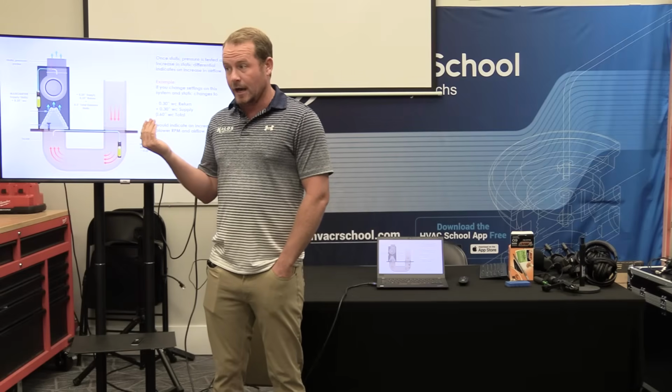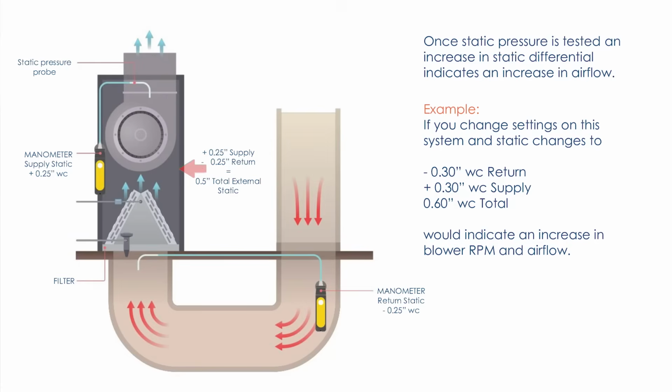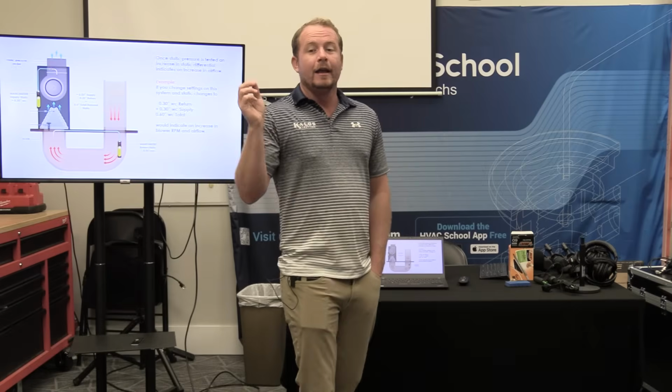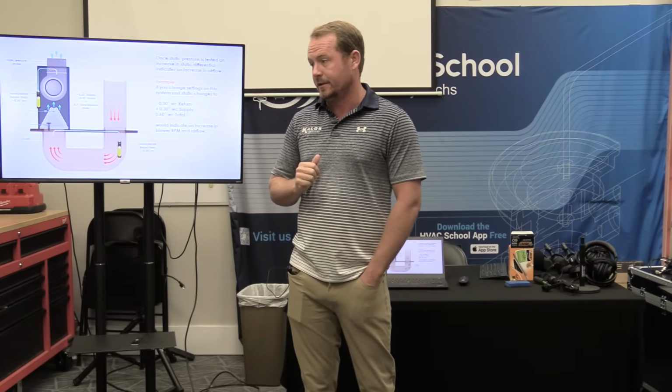This isn't something we do a lot, but the easiest way to do this is to make a penetration, a tiny hole between the furnace and the coil, usually at the top of the furnace. There's whole videos on how to do this, for any of you who have never done this before. And you take a measurement from the bottom of the coil to the top of the coil, and now you don't have to take it apart to see, is this coil restricted?